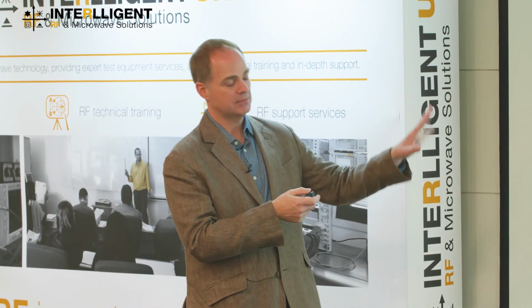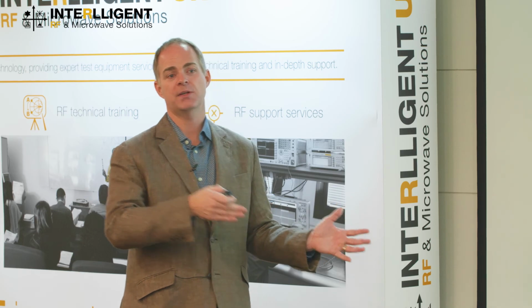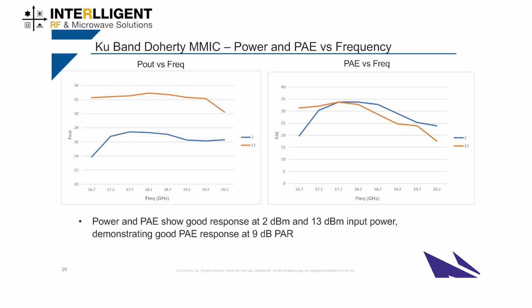So excellent results for a Doherty in general, considering the bandwidth, but particularly considering that it's at about 3 times the normal frequency use of these things, and it's in a MMIC form, really exceptional. And then again, we can see the back off and full saturation peak operation. P out of, again, a little better than 32 dBm, and then 27 dBm for the back off, and you can see that we're maintaining that efficiency across the band.